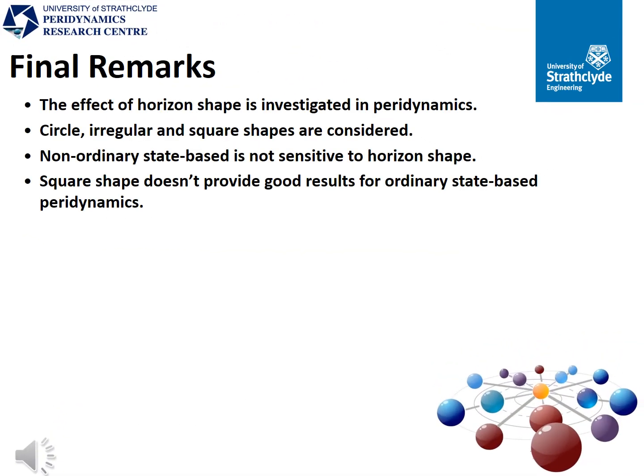As a final remark, in this study, we investigated the effect of horizon shapes in peridynamics. We considered circular, irregular, and square horizon shapes. Our findings show that non-ordinary state-based peridynamics is not sensitive to horizon shapes, and the square shape doesn't provide good results for ordinary state-based peridynamics.